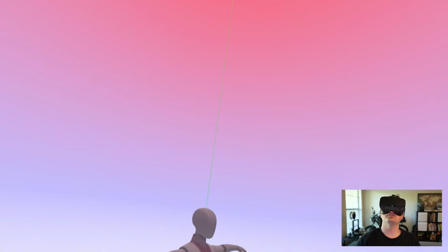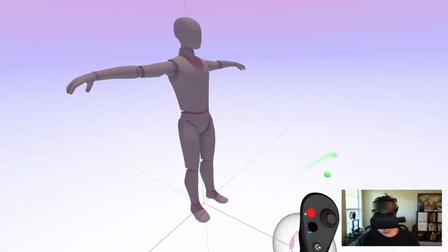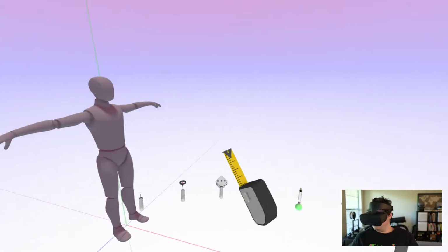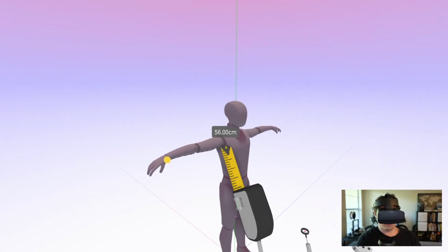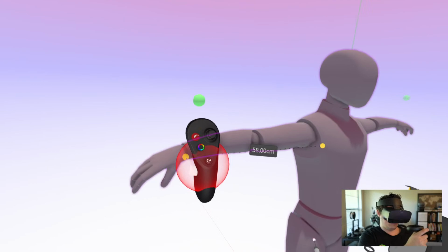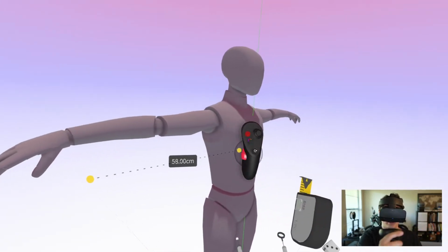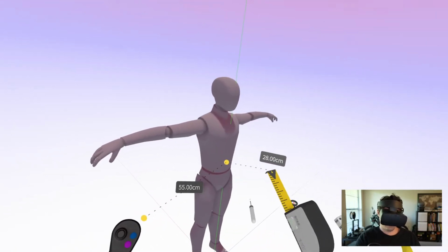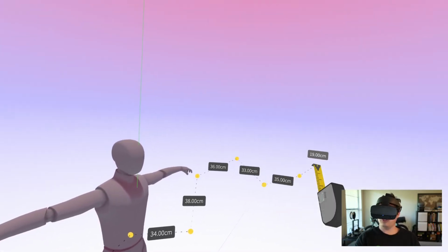Basically, you're asking if you can edit what you drew with the measurement tool, can I now go in and grab this point and move it out of the way? The answer is no. It's just floating there in space, and as soon as you draw another one, it disappears.